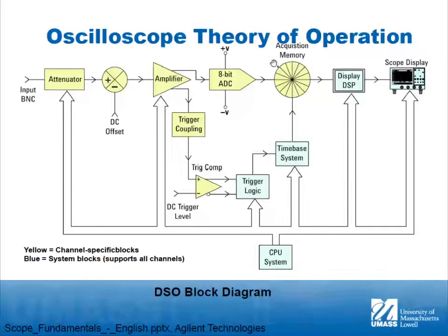Depending on the position of the trigger, it reads out this memory into the display. Right? So I have this continuous window, this history of the signal, and I read out the position of it relative to how I set up the trigger, right? The trigger at the end, at the beginning, and the middle, right? We saw some examples of that here. And triggering is going to be important. And when we do large digital analysis, we're going to really want to do complicated things with the trigger. And again, that's kind of the point that I'll get to tonight. All right.